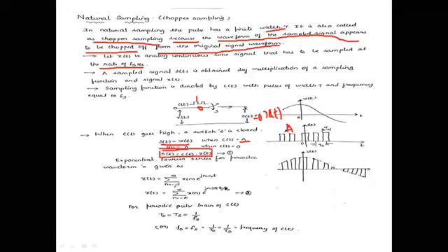So what is c of t here? It is the sum of n equal to minus infinity to infinity of c n e power j n omega naught t. This is according to the exponential Fourier series synthesis equation, saying that c of t is equal to the sum of n equal to minus infinity to infinity of c n e power j n omega naught t, where omega naught is 2 pi by T naught, or 2 pi f naught. For the periodic pulse train c of t, T naught is equal to Ts, or 1 by fs, my dear students. I have taken here an exponential function, and this is the synthesis equation. For the analysis equation, the exponential is a negative value, my dear students.